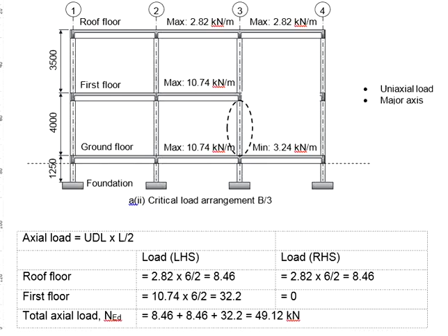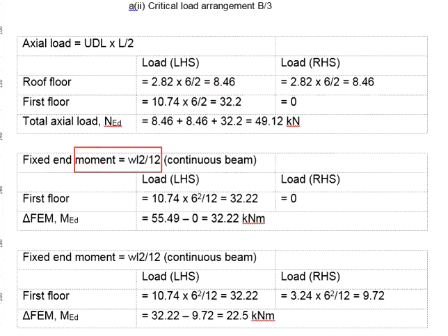In order to do so, you will need to first determine the moments to be taken by the two joints. Let us deal with this joint first. Get the fixed end moment for the beam here. Since you don't have a beam here, the moment taken by this joint will be purely governed by this fixed end moment. We calculate the fixed end moment, assuming the beam is continuous throughout. The formula will be WL square per 12.